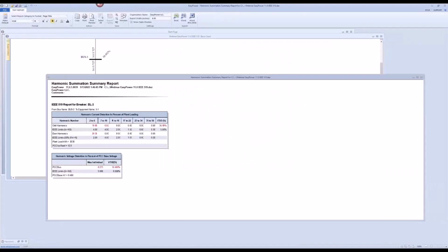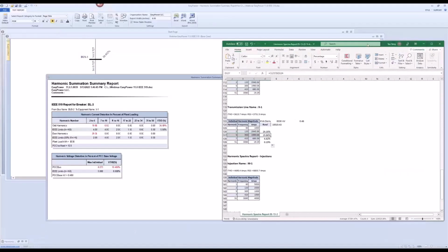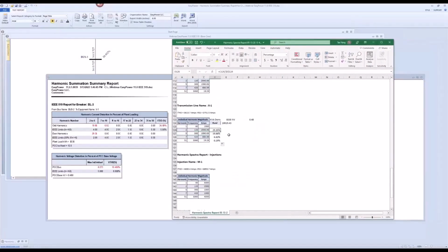with my summary table, right? I know that my second order is 29.35 based on my hand calculation. Even harmonics within the range. That is the second harmonic order, right? 5th is 19.86. 7th is 6.82. 51st, oops, I don't have it because the IEEE 519 limits at 50, right? So I don't have it anymore, but I can still calculate if necessary. So this is the way that engineers can build your report.